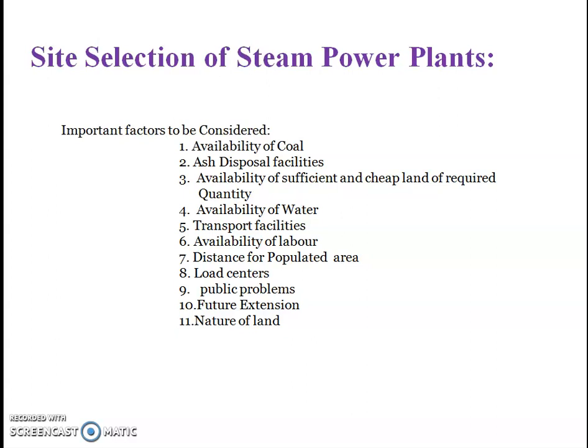Ash handling is a serious problem as it comes out in hot condition, is highly corrosive and pollutes the atmosphere. Therefore, sufficient space must be available to dispose of a large quantity of ash. Presently, efforts are being made to use ash in road construction, brick making and other processes.